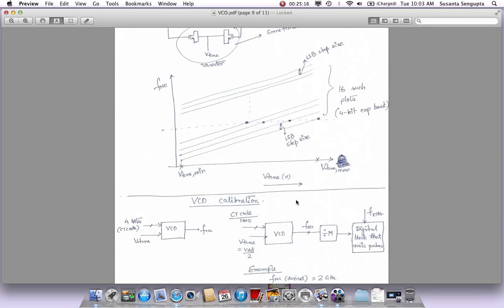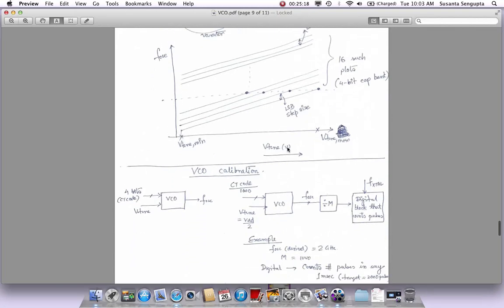Now this will clear up more of why we want this, because it has to do with something we call VCO calibration. VCO calibration is a step that happens, I think, in most of the cellular products. When you wake up, the digital knows that I want to lock to this channel, and when you wake up the chip, first when you power up all the blocks, even before all the blocks have settled, in case of the VCO, you will just not turn it on and start this.